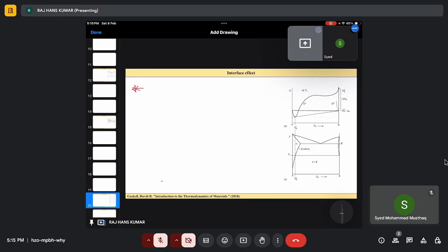Okay then. Now the solubility is very low, such that my G versus X curve. Suppose this is my XB equals 1. So my solubility is very low, such that my G versus X curve will look like this. Okay. So this is my other vertices. If my tangent is there, then this will touch at mu B, the chemical potential of B in beta. Now what is this point? This point is my free energy of B in beta form.